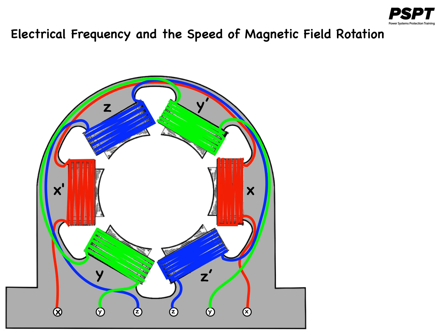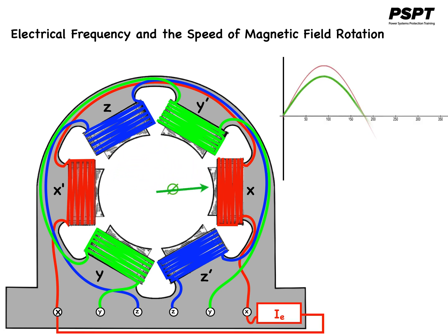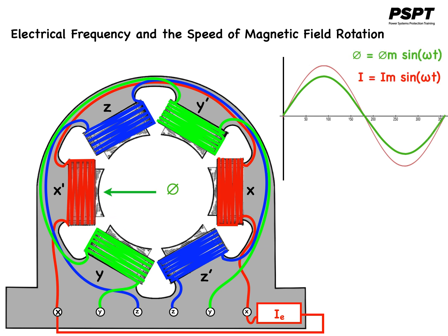Let's take another look at the rotating magnetic field in this stator. As we have just seen, in a 2-pole per phase machine, the rotating field is in sync with the electrical supply. In order to differentiate between the supply and the rotating magnetic field, I'm going to refer to the supply oscillations as electrical, and I'm going to refer to the rotating magnetic field as mechanical.